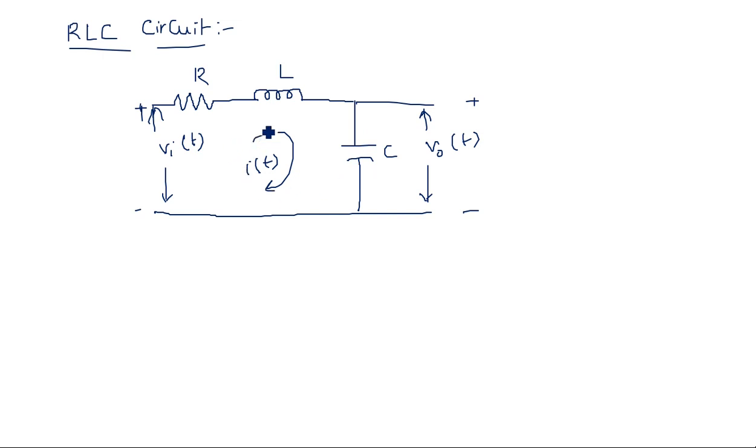It is also like a filter. RL, RLC, RC, all these are filters. LC, these are filter networks. Whenever the combination of capacitance or inductance comes into the circuit, definitely that particular network acts as a filter. Now let us calculate the output voltage and what are the different possible output waveforms that come from this particular RLC circuit when a step input is applied.